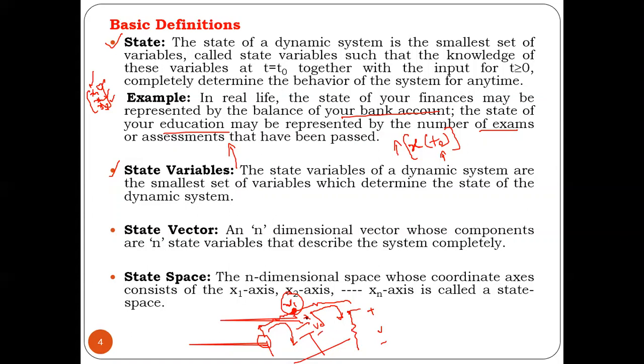Not required, because these two voltages are the same. Separately, I would say V1 is a state variable and VC also a state variable. But when I consolidate these two, I feel one is sufficient. That is the optimal variable. Only one variable is enough, and that variable will be included in the state. Duplicates we should not take. Either V1 or VC we will take in the state.